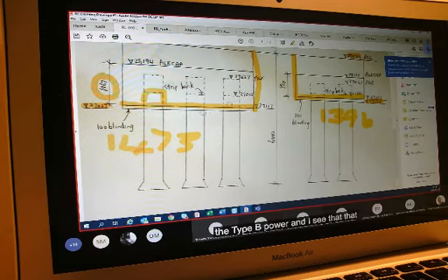By the same token, I need to calculate the reinforced concrete in the type B pile caps. I see that the dimension given to me over there is 990 millimeters, or 0.99. So my dimensions there would be 2.13 by 0.91 by 0.99, and I have two type B pile caps, so my quantity to measure for the concrete is times 2.